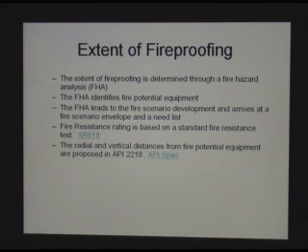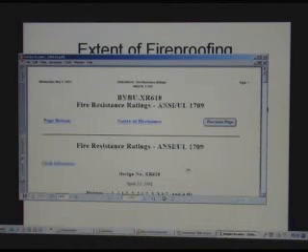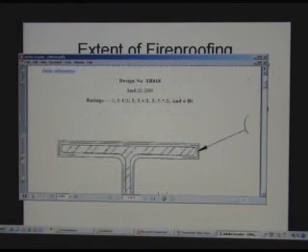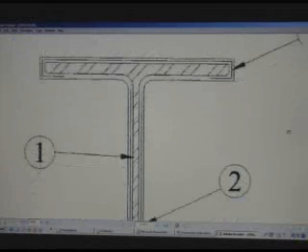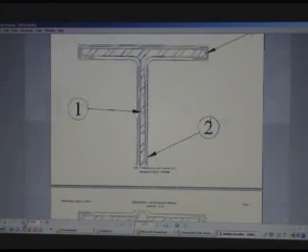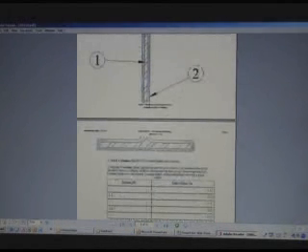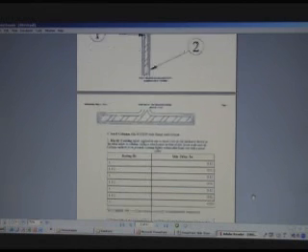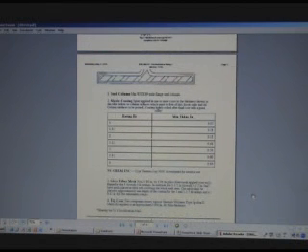And can you click on XR 180? This rating is material specific and is certified by Underwriters Laboratory based on a UL 1709 test. And this tells you exactly how to apply the materials to get this rating. And you determine, let's say you want to have a 3-hour rating, you need to apply 0.6, I think, inches of this material to get the 3-hour rating.